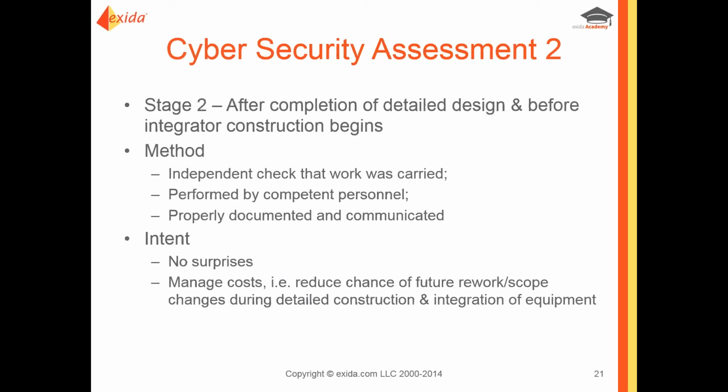At the end of the detailed design phase, just like in the functional safety world, where they have functional safety assessments, as part of those or as separate activities, you should be doing cybersecurity assessments. And at this stage, this is stage 2. It's right at the completion of detailed design, but you want to do this before the integrator begins their work in their shop. It should be done independently, needs to be done by competent personnel, and properly documented and communicated.